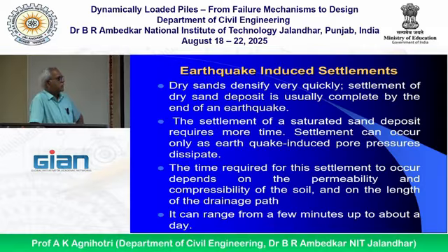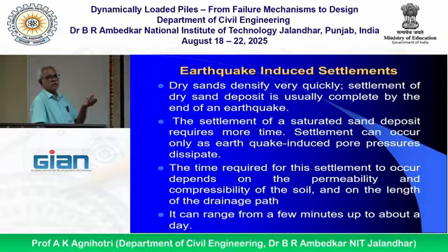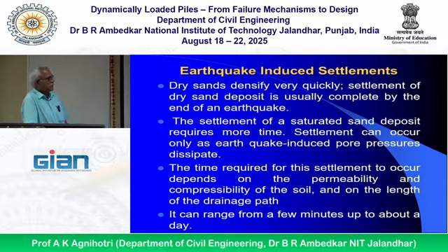Settlement can occur only as earthquake-induced pore pressures dissipate, because immediately due to earthquake there will be a sudden increase in pore water pressures. So that depends upon drains provided, length of drain. If there is dissipation of pore pressure in small time, then settlement will be in small time. Otherwise settlement will take more time. Time required for this settlement to occur depends on permeability and compressibility of the soil and on the length of the drainage path. It can range from a few minutes up to about a day.